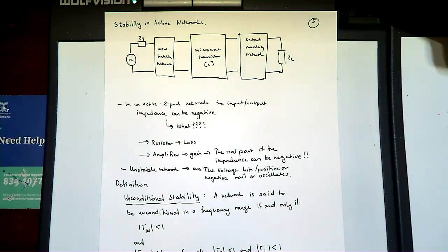Right. It can never go, it can go a little bit, so it's really the supply range, right? Now, technically, you might have ringing, so you might go a little bit above the rail or a little bit below the rail, but generally you don't go much above or below your supply voltage rails. So, unlike control theory where you've got a pole in the right-hand plane, which, if you do the mathematics, goes to positive or negative infinity, depending on whether it's oscillating.